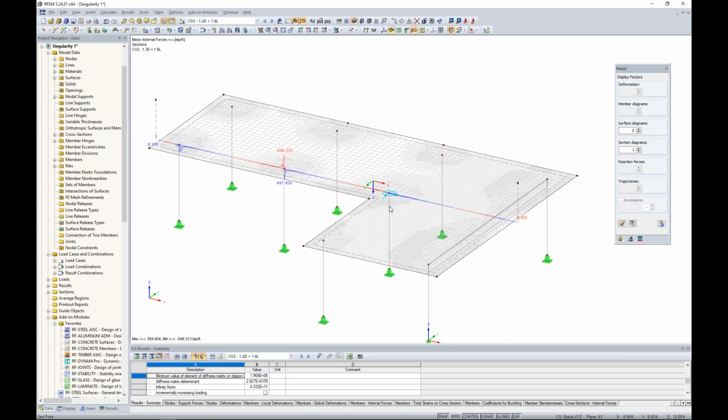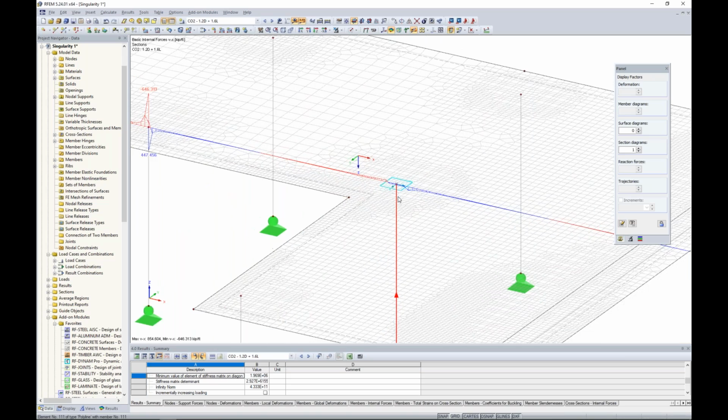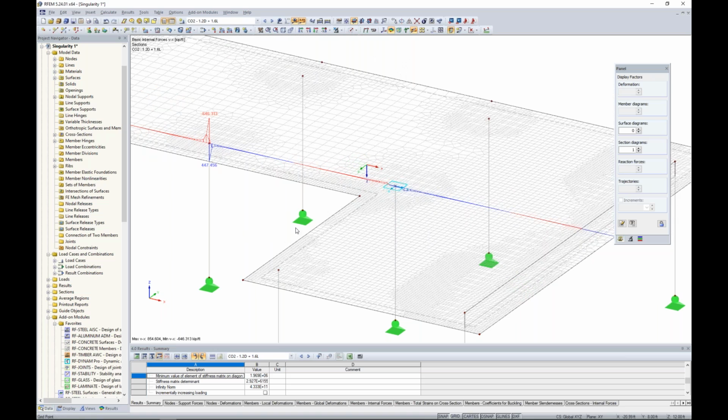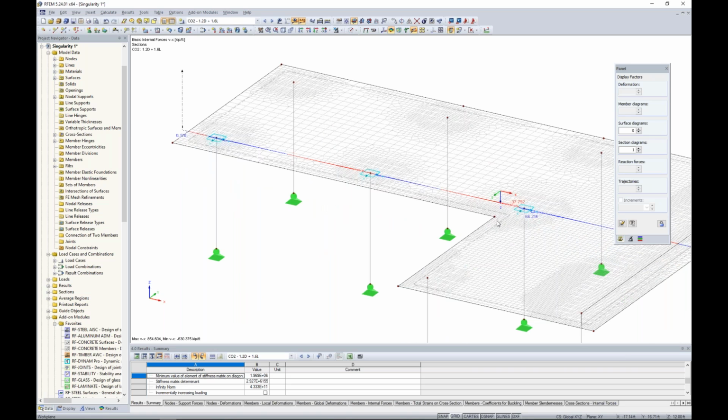So now when I click OK, you'll notice that immediately that high peak force is gone because we're averaging it out over this entire area shown with that blue symbol. I can take this average region, hold down my control key, drag and drop it to my next column location. You'll notice that peak's now gone. Let's continue to do so with this third column. And now we're seeing those high peak stresses are eliminated.